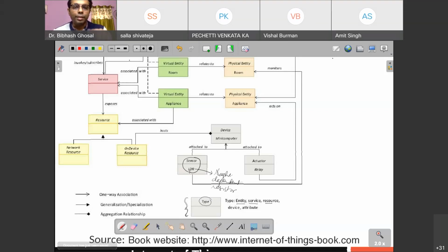Okay. And that is an indication that there's some electrical quantity that has been designed, which is obtained from a variation of the physical quantity, and that is provided to you. So the variation in the light is equivalent to variation in the current, and that is what is provided as the data. So if this is calibrated, let's say some change in the light will equally be reflected as change in the current. So this is the sensor that will pick up the light information.